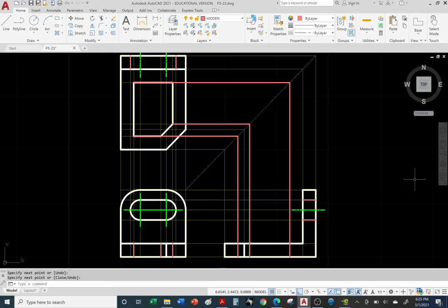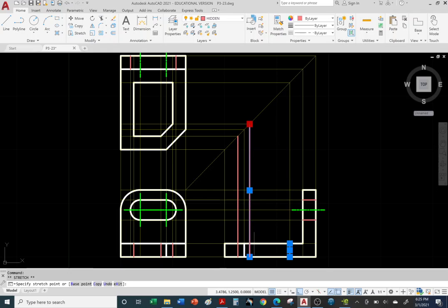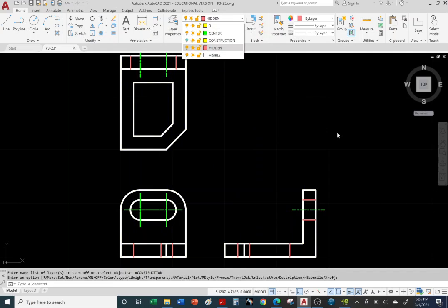And there it is. We have our red hidden lines. Let's get rid of the evidence that we cheated. So let's select these 2, or I should say 3 hidden lines that we don't need. Use the pencil eraser to delete. And now we can shorten the other 3 to the correct length using the grips. All right, looks like we're done. Hit Escape to deselect. Let me turn off the construction lines. This is optional. There it is. Clean it up.